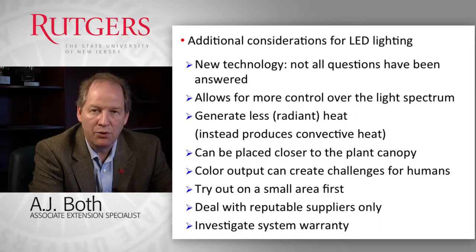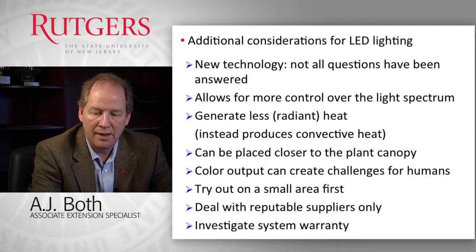And I think it is important to investigate the warranty that these suppliers provide on their systems, and you should know whether the warranty includes the LEDs themselves or the entire system. And I recommend that you try to get a warranty on the entire system that includes the drivers as well as the other components that are needed to operate an LED lighting system.